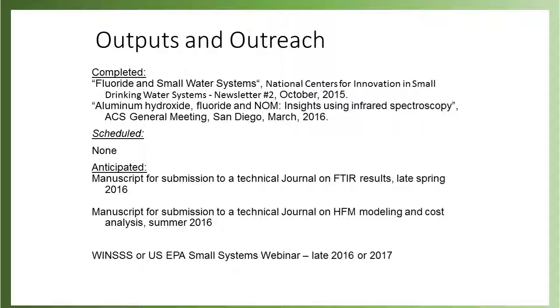One of the interesting things, to use the term that John hates, part of the enhanced coagulation rules is this business about how you don't have to go farther than the point of diminishing returns. It turns out that when you have fluoride in the water, you reach the point of diminishing return way early.